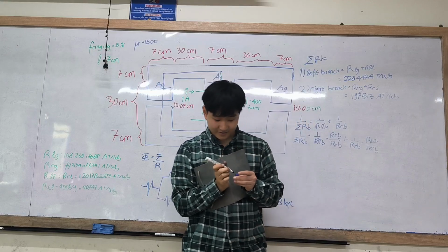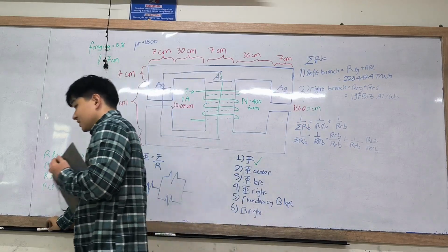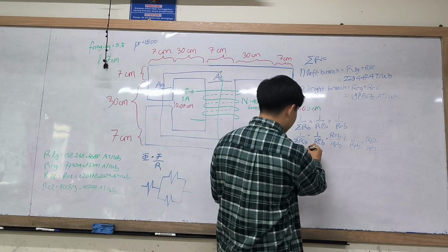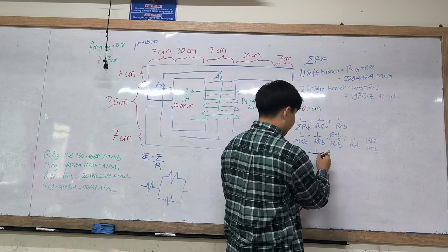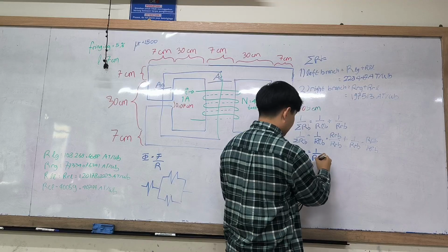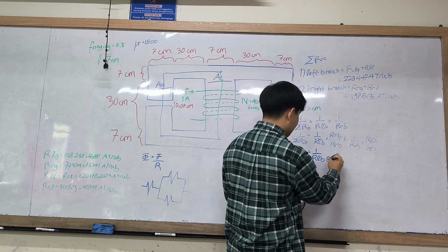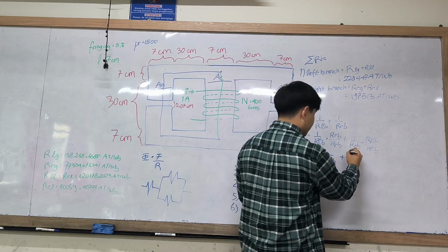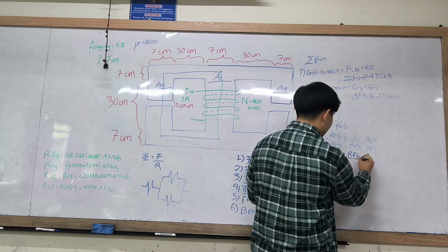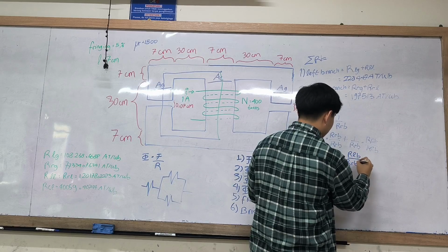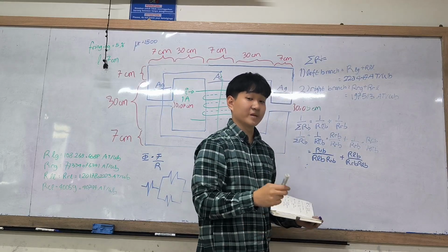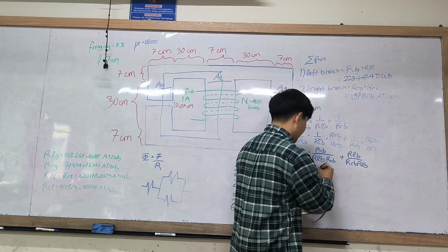The ink is dying, so I am going to use another blue marker. The result will be 1 divided by the reluctance of the left branch times the reluctance of the right branch, plus the reluctance of the left branch times the reluctance of the right branch. They have the same denominator, so their numerators can just be added like this.